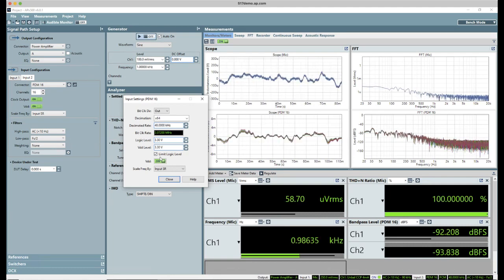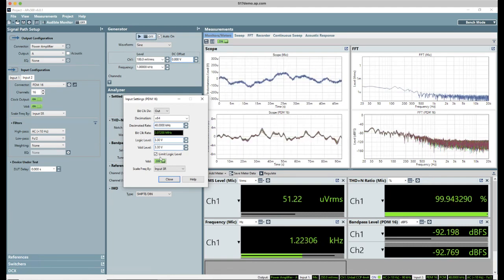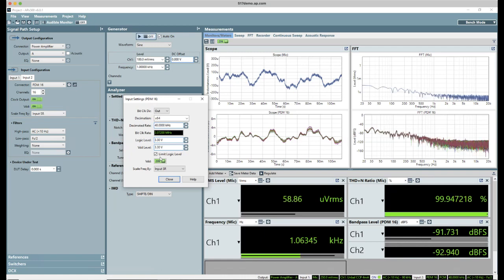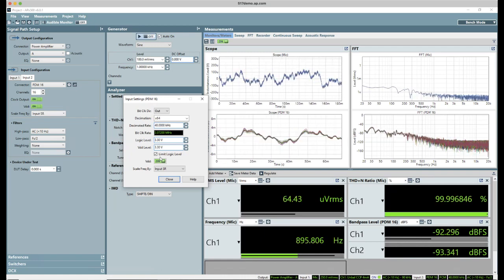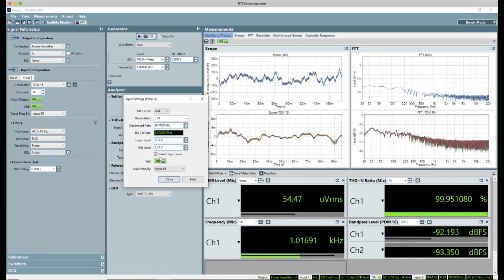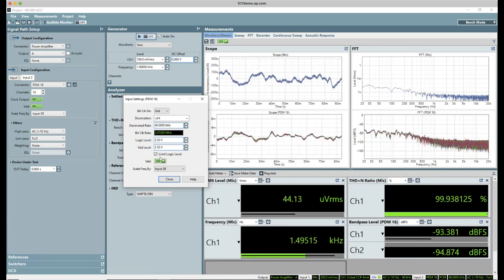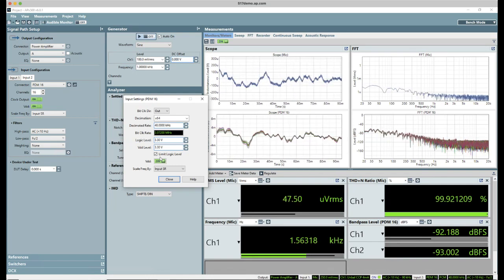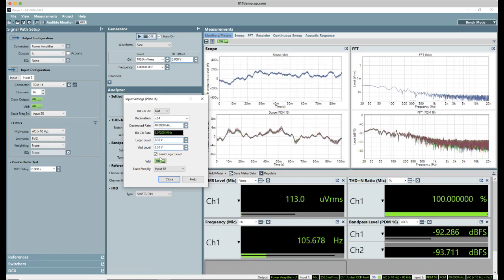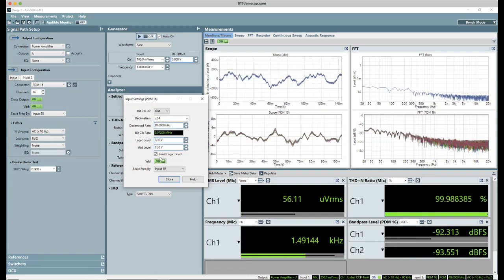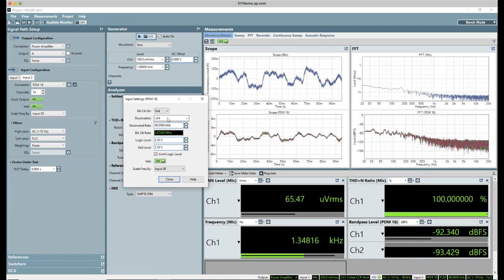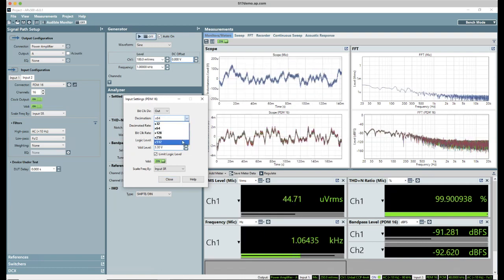And it comes out at a pretty high rate. So in this case, in my current configuration, it's coming out at 3 megahertz. And we then decimate or low pass filter that to actually demodulate the baseband audio. And the question is, well, at what rate should you do that?